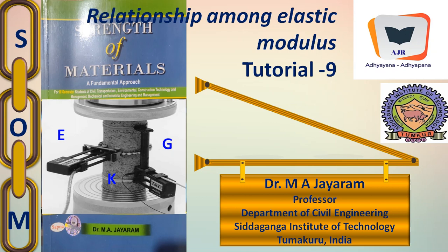The G, the rigidity modulus, as the name itself would imply, is a measure of capability of materials against dislocation of points in a component, a kind of angular deformation, which will bring in total deformity, total changes in the shape of a body, unlike the linear deformation. The third one, the K, the bulk modulus, is the measure of capability of materials against volume change.